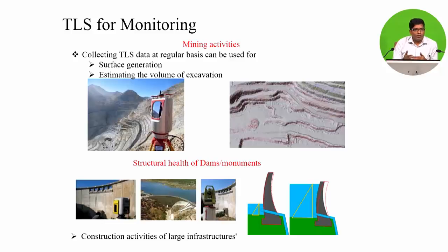And for a mining site, we can generate the surfaces at regular intervals, and then by comparing these two surfaces which are acquired at different intervals, we can estimate how much volume is excavated, and accordingly the monitoring of this can be done. Apart from the mining, we can also do the monitoring of the structures.